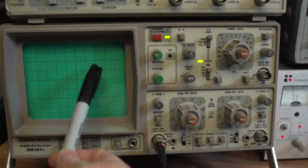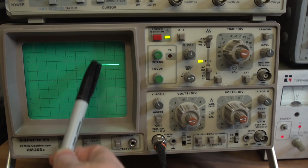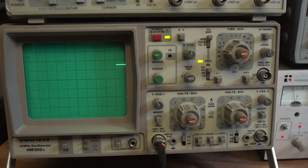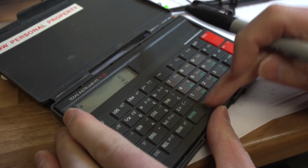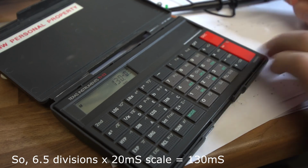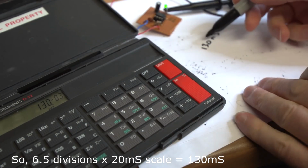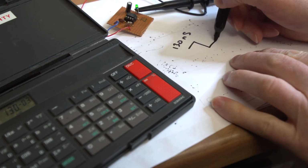6.5. It's in the middle of a graticule there. So it's 1, 2, 3, 4, 5, 6.5. So it's 6.5 multiplied by the 20 milliseconds. Okay, you can probably do it in your head, but let's get the calculator. So 6.5 times 0.02, which is the 20 milliseconds, and that's 130 milliseconds. So that's our time period, 130 milliseconds for a totally repeating waveform.